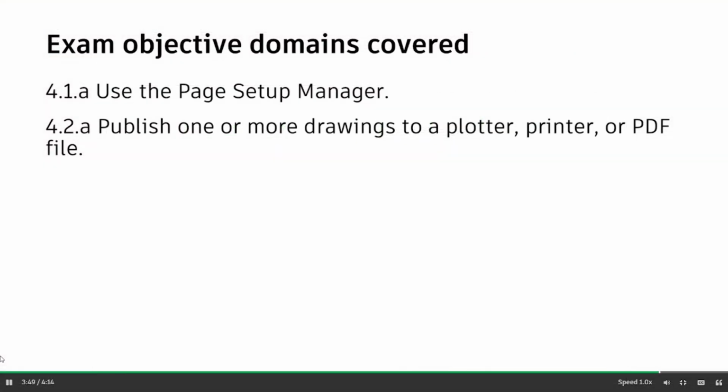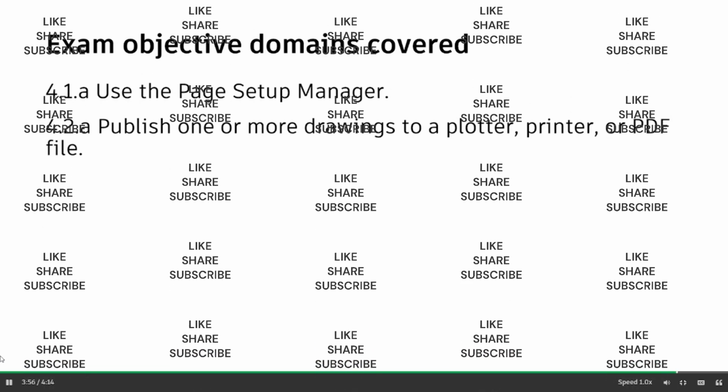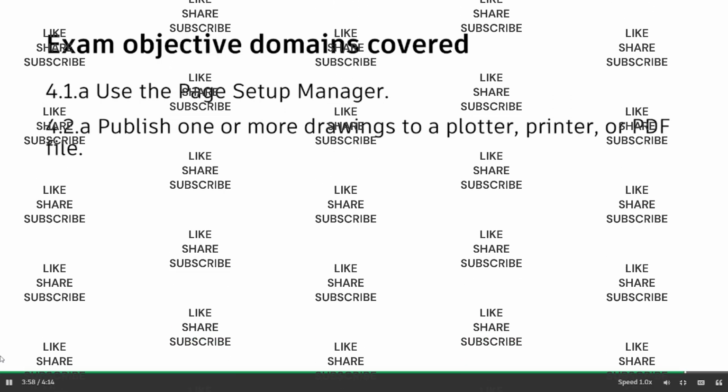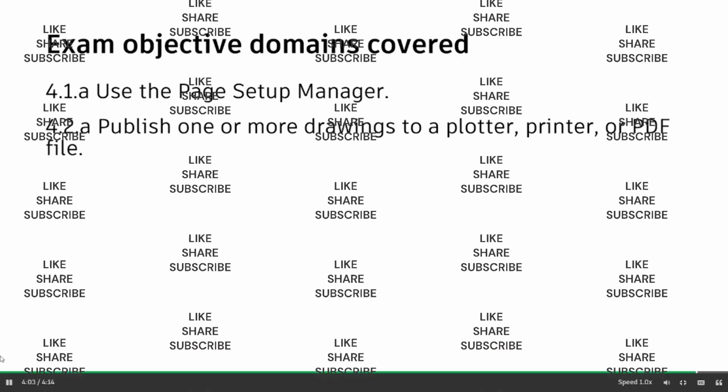In this lesson, we used page setups to control how layouts would be plotted and used the Batch Plot tool to plot several layouts in a drawing. Batch Plot can be used to plot more than one drawing and more than one layout.